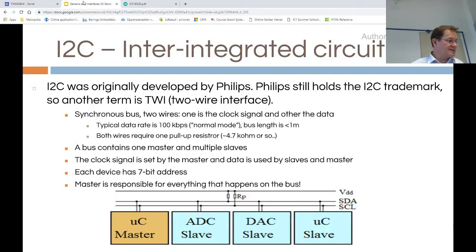But anyways, that's enough in any case, since you don't usually need more than tens of devices in one bus, especially when you think of this kind of bus which has an asymmetric line, meaning strong 0 and weak 1 state.